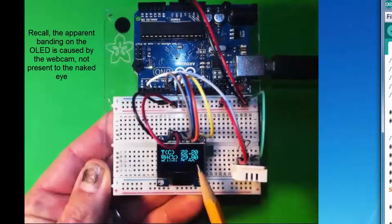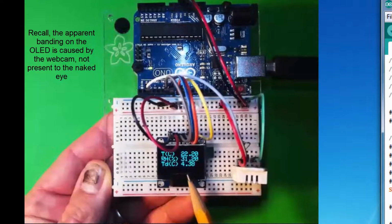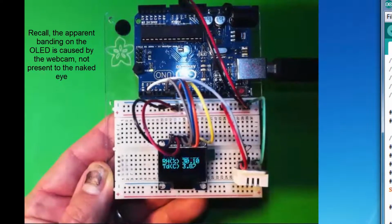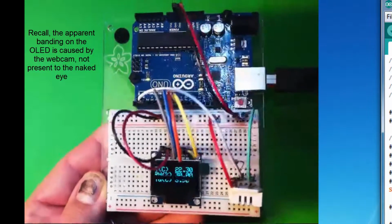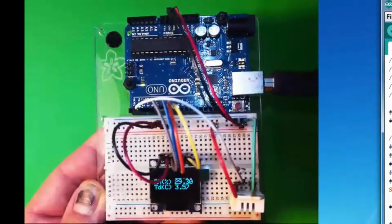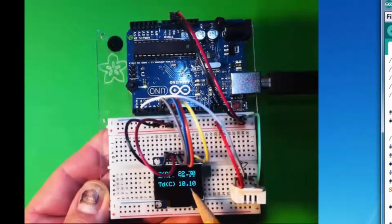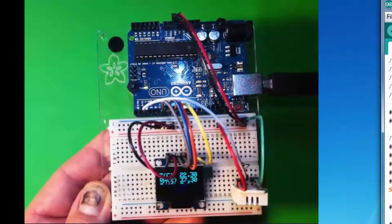Temperature is 22.2 degrees. Relative humidity is close to about 30%. And the dew point is 4.38 degrees. That makes a lot of sense for as dry as it is in the room. If I blow on the sensor, see it responding, humidity jumping up to 45 and the dew point going up like we would expect.